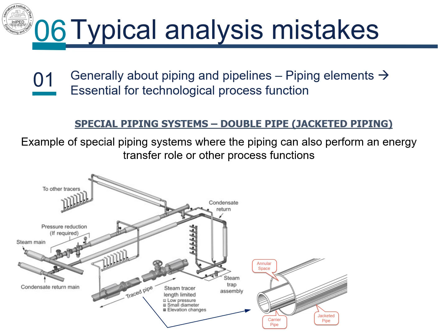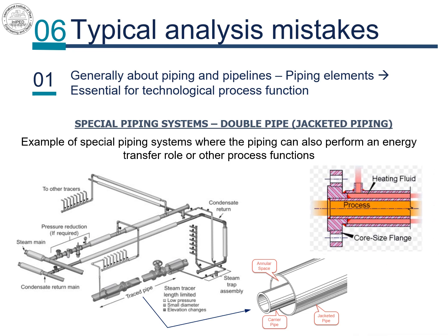Heating medium flowing through the cavity between the core pipe and the jacket can be steam, hot water, hot oil, or some other heating medium. Bearing in mind that in this case, outside and inside pipes, which form the whole, have different operating temperatures, it is obvious that different thermal expansion problems can occur. Therefore, it is necessary to solve these complicated challenges of thermal expansion compensation, while maintaining the piping stresses within the allowable limits. Jacketed lines can be mounted with or without elements for thermal expansion compensation. And supporting problems are similar to those of single piping non-jacketed systems.